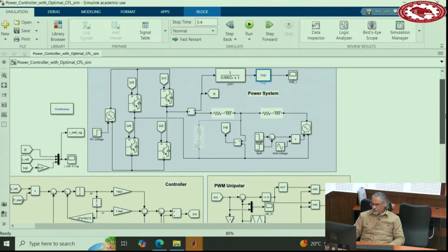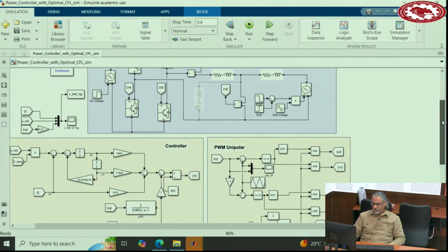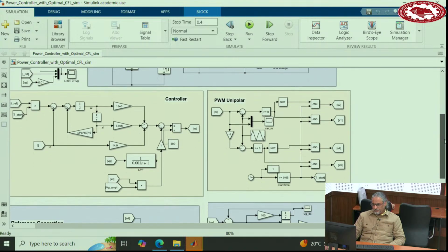Okay, so here is the AC grid, and here I applied voltage drop in the AC grid and those things, so we use controllable voltage source. This part is the PWM, it's a unipolar PWM. This is the controller, which I reference comes here. There is a T start, because we want to wait a little bit and then start. So you need to define a start. So a start at that point multiplies in this one, and then minus the current. This is the resonant controller.